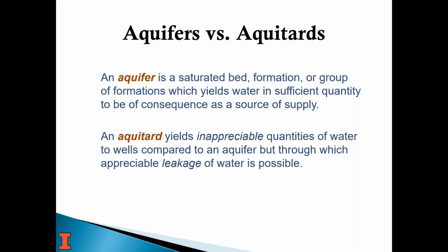It means it only pumps, if it pumps any, like the soil for where you put in a dug well near the surface. A lot of times there's no sand and gravel well there, there's no bedrock well there. It's a large diameter well because it has to store water. It won't let water move fast enough to actually be usable to a pump while it's on in a well. And so an aquitard is really the finer materials or the solid rock that doesn't let water get through it, or not in a quantity that promotes well use.